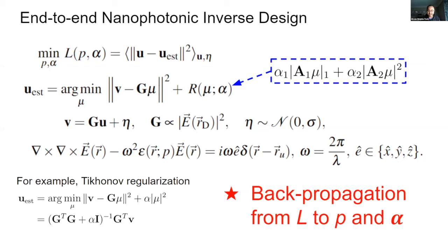To be precise, compressed sensing says that the best possible measurement matrix is one that has the restricted isometry property, which is basically like random Gaussian matrices, right? But you have to realize that a random Gaussian matrix doesn't really mean a random structure. If you just put a random structure, you will find that your measurement matrix G leads to a very non-random PSF.